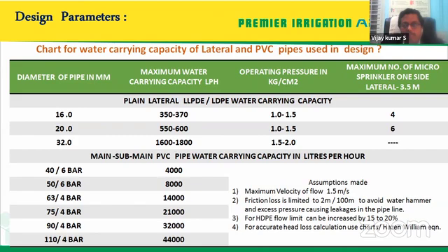Why do we do that? Like I explained to you, you'll have what is called water hammer. Water hammer means water will come and hit, and you will have a rebound, and when the rebound is there, you could have leakages from the joint. So basically, we want to send the water in a very smooth way.